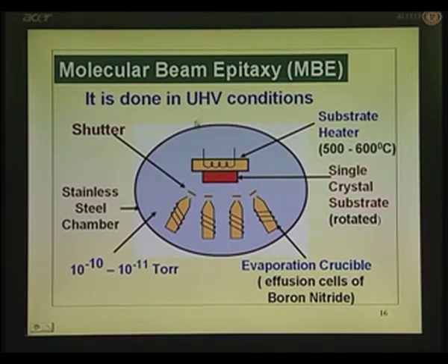And okay, so the constituents of this MBE system are these K cells, which are the sources of evaporant with shutters which can be opened or closed whichever you want. All of them are heated. You close it, all the things you close. If you want only gallium arsenide, open only these two shutters. Okay, that is the idea. And these shutters can be computer controlled.